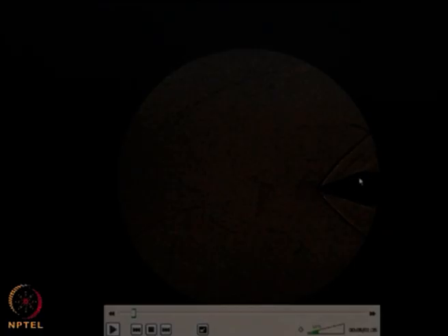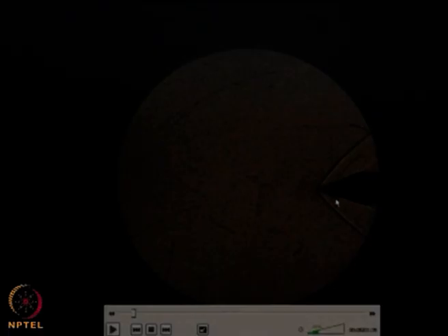Because of those grooves, you can also see the Mach waves inside here. In this region, you will see tiny waves creating small disturbances. It is like a small hole and back to normal, small hole and back to normal, so you will see those tiny things. It is not very clear on the screen, but you can see very clearly the oblique, attached shock that is formed for this particular flow field.